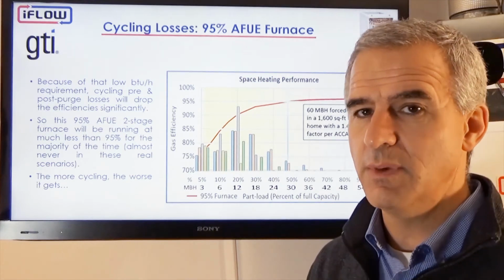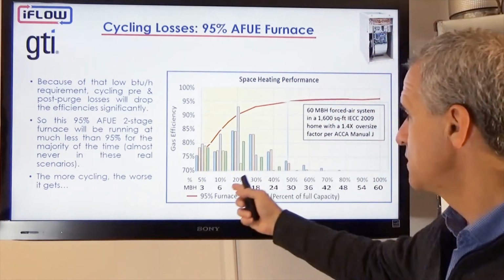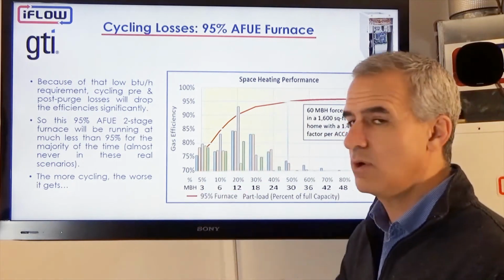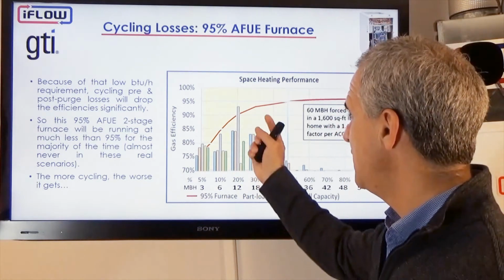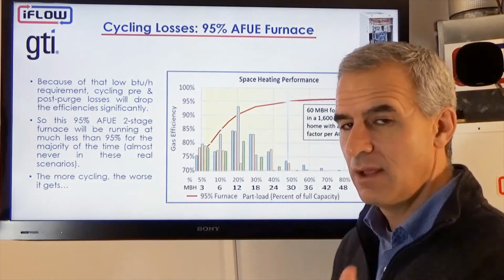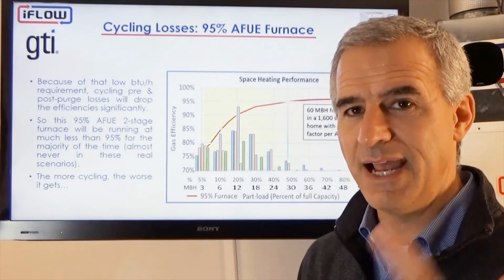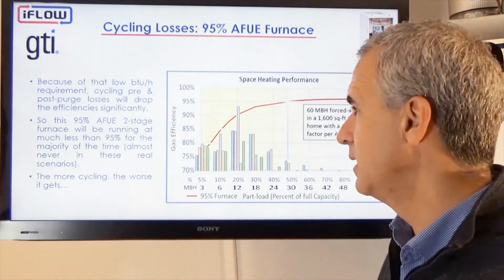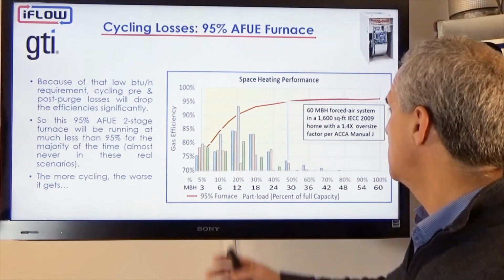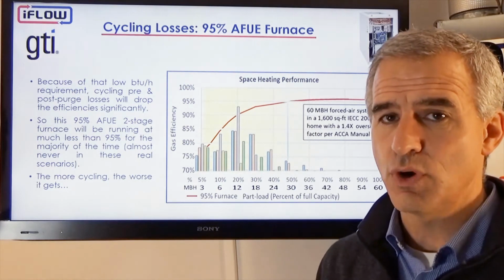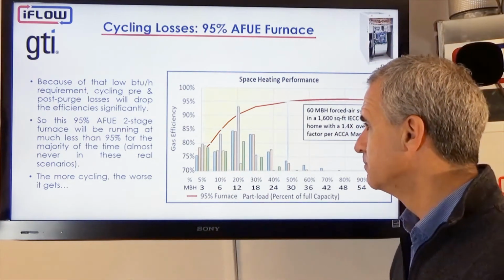You're not going to be comfortable with the furnace operating that way, and then your efficiency is going to drop to make it even worse. So now you've got two situations. You're not comfortable and you're paying more because your unit's cycling. That's not great. It's not sized properly for the application.